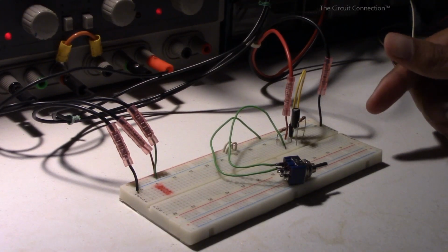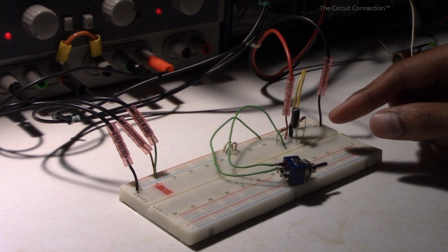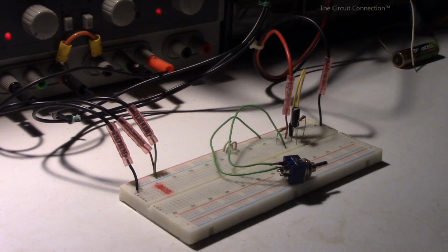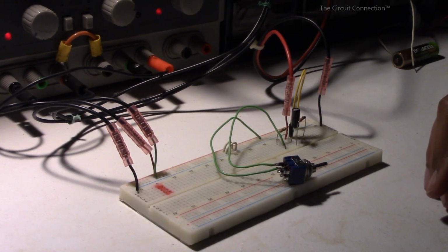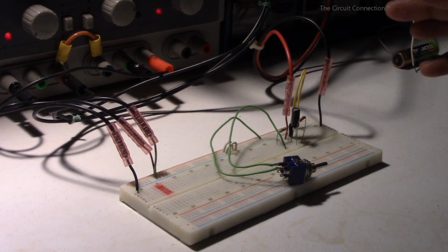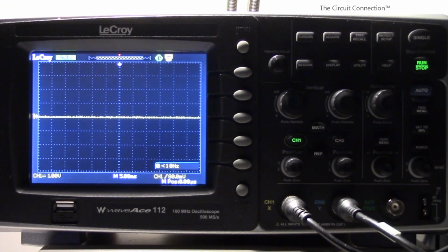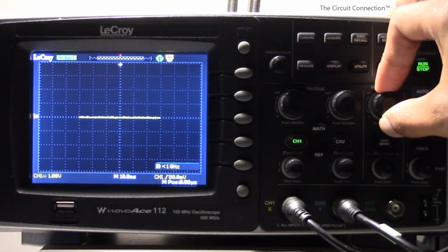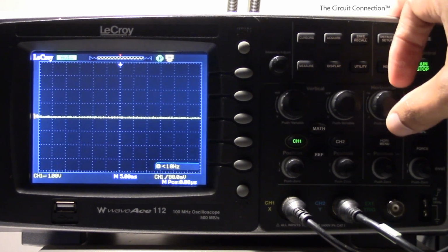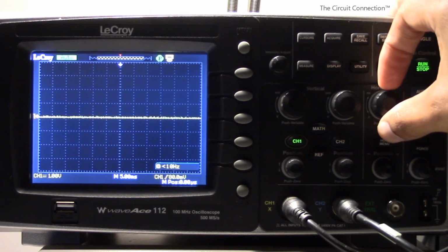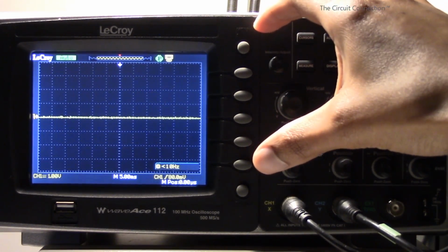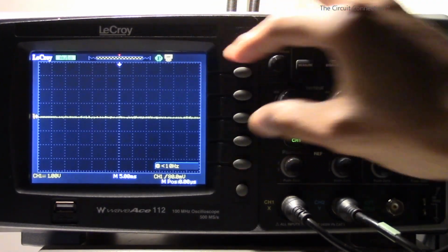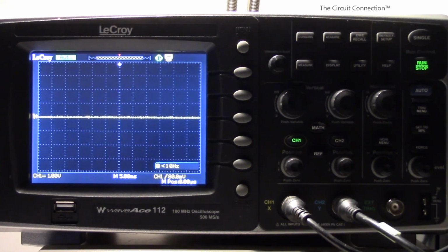This is my breadboard build setup here. I have my 2 resistors, my capacitor, and I have my 5 volts there. I have all of that set up, and so the next thing is to take a look at the oscilloscope settings. First you want to make sure that your time divisions, which is your horizontal knob, that your time span is set correctly. I have 5 milliseconds per division, just as I did in the simulator. As far as my vertical is concerned, I have 1 volt per division, and I have 4 divisions, so I'll be able to see a full 2.5 volts there. It won't look too small, but it won't be off the screen either. So those are appropriate levels for that.